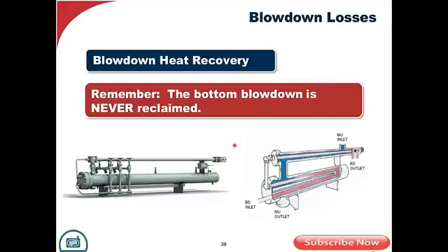Our water chemical engineer has advocated a certain water treatment plan to control the total dissolved solids. That boiler is skimming water off the top, and it either goes through a separator and into the sewer, or it can go into a shell and tube heater and recover those BTUs, put it in the feed water before it goes to the deaerator or feed system. Why not reclaim those BTUs?